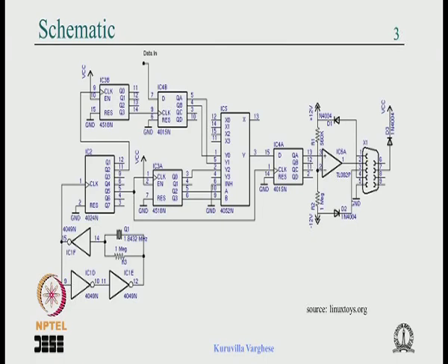Then we partitioned it into a level 1 partition, still black boxes: ALU, registers, program counter. Ultimately when we broke down into known pieces, it came to gates and flip flops or some known blocks. So this was one difficulty with the schematic. A hierarchical or top down approach was not possible.